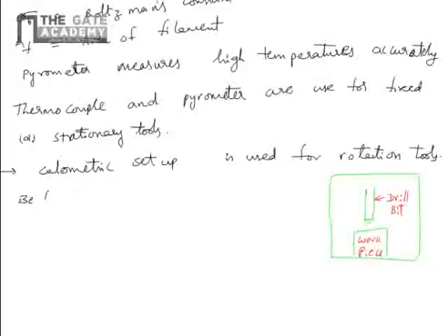Before the drilling operation, the heat equivalent, or temperature inside, is determined and measured. The drilling operation is performed for a few seconds, so that the heat generated in the machining operation is taken up by the calorimetric setup.